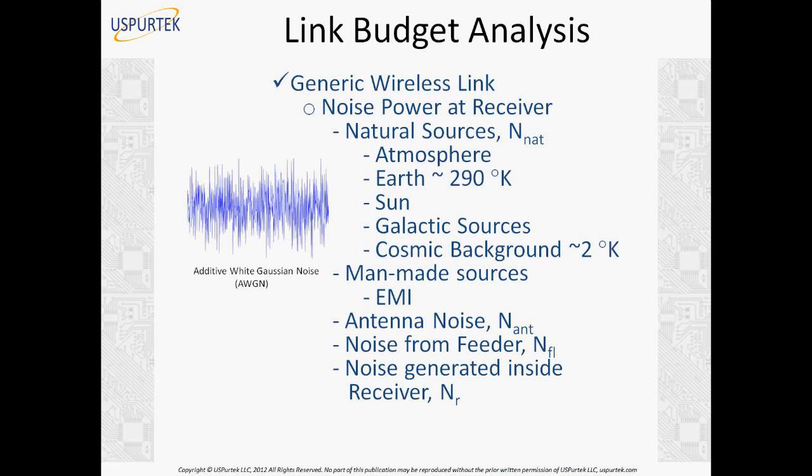I'm trying to simplify things here. Like we have a transmitter on one end and a receiver on the other. It's not actually like that. We have transceivers on both ends, both a transmitter and a receiver on both sides. So if you have a transmitting antenna and a receiving antenna side by side, of course the transmitter antenna will also contribute to the noise, which will be picked up by the receiver on the same side, right? So we are not talking about just the receiver equipment, but the transceiver equipment, which includes all the transmitting devices and the receiving devices. All of them together will generate noise. That has to be accounted for. Okay, thanks for the clarification.